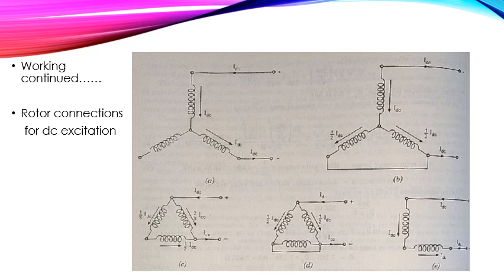So the actual fact is that a synchronous motor needs a heavy excitation to enable it to operate on a leading power factor. The relatively larger air gap, though, results in a low power factor when operating as an induction motor, but at normal speed this is immaterial, since the power factor can be controlled by variation in DC excitation.